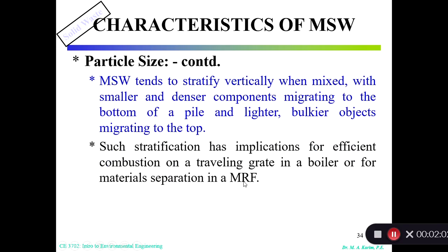So MSW tends to stratify vertically when mixed, with smaller and denser components migrating to the bottom, the same concept as in other cases. Such stratification has implications for efficient combustion on the traveling grate of a boiler, or for material separation in the MRF, material recovery facility.